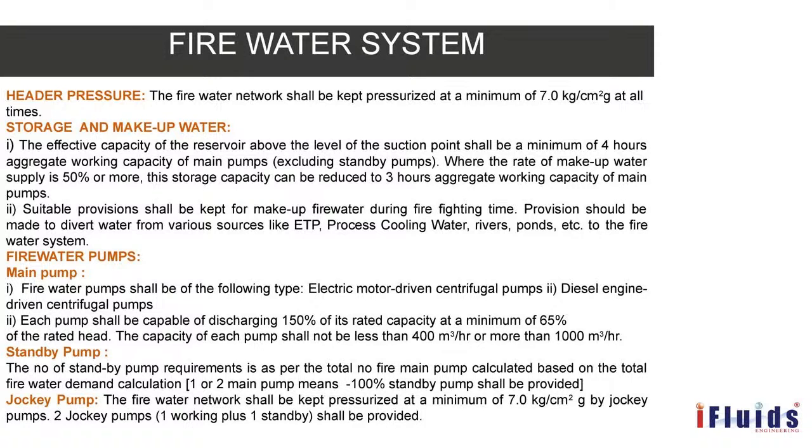calculation. If your total fire water demand calculation is deriving one main pump or two main pumps, then the same amount of standby pump has to be procured or provided. If it is more than two, then 50 percentage of the standby pump should be provided. If it is jockey pump, then the significant point which is mentioned in jockey pump is that the